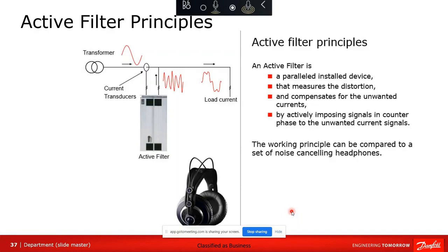We said if you put a 400 amp active filter at that MCC panel, it will mitigate all the harmonics from those 8 drives on that system. And we did that in 2 different sets. So we have a 400 amp filter, 8 100 horsepower drives, no problems with harmonics at all. And then we have another duplicate set on another system.